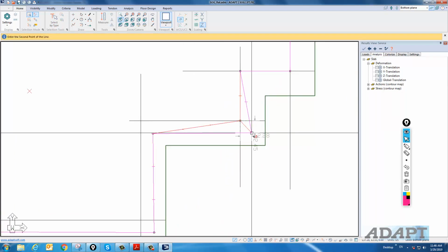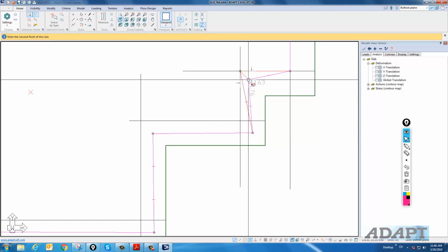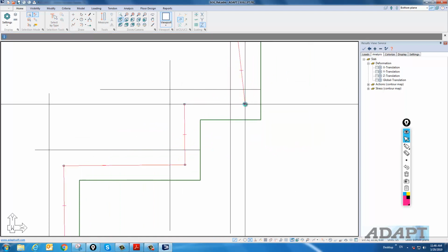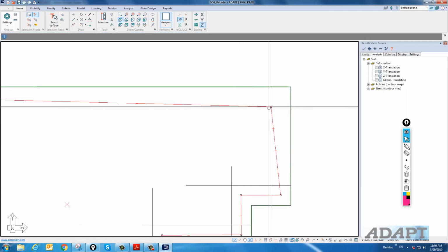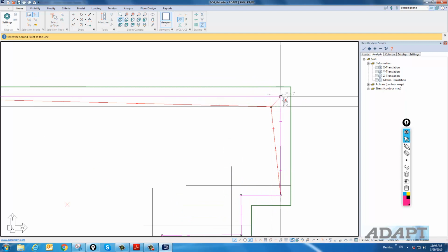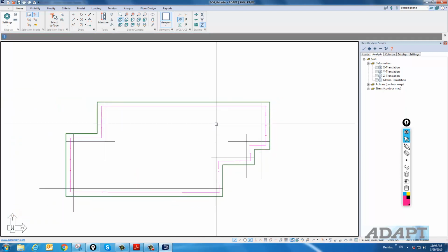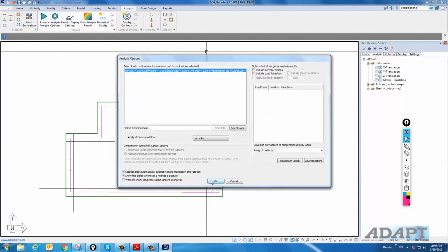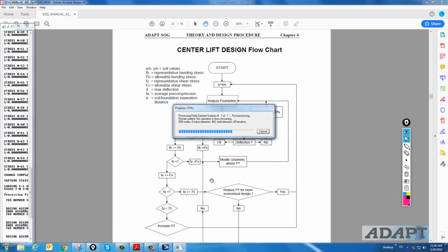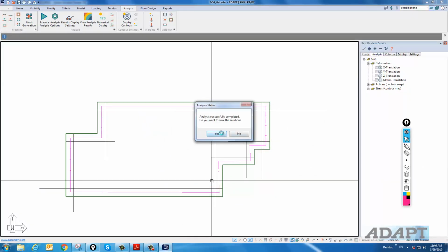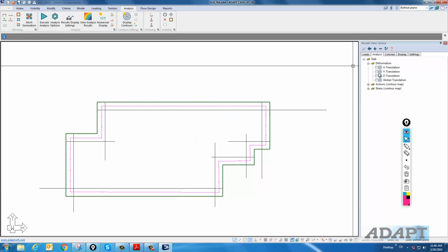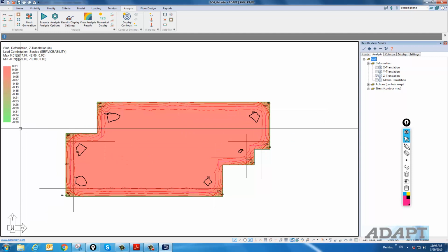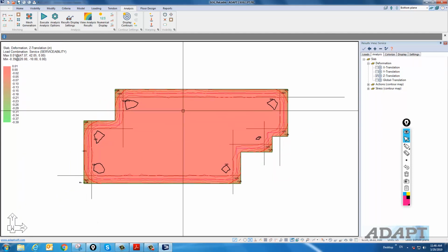And this might represent maybe 2 or 3 iterations, but we're just cutting that in half and saying, well, we know we have to come down this far anyway in terms of the offset to get a workable solution. So we reduce the offset and we rerun the analysis in order to correlate the proper edge moisture distance with the expected vertical movement and response of the slab. In this particular run, we now have 0.39. So this is close enough for us to continue on and check stresses.